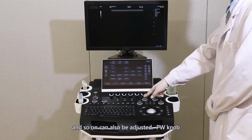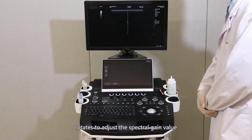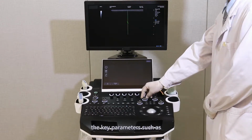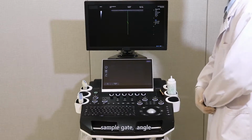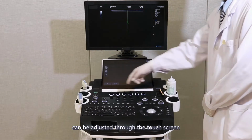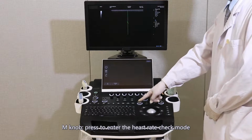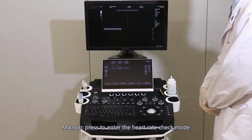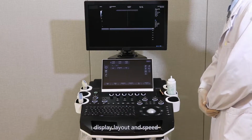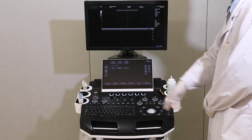PW knob. Press to enter the pulse Doppler. Rotate to adjust the spectral gain value. The key parameters such as sample gate, angle, and display layout can be adjusted through the touch screen. M knob. Press to enter the heart rate check mode. Update button to refresh. Display layout and speed can be adjusted through touch screen.